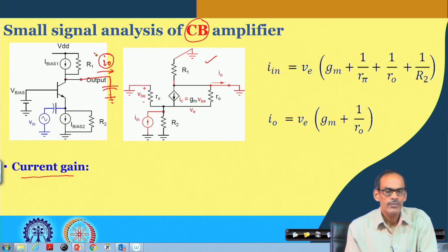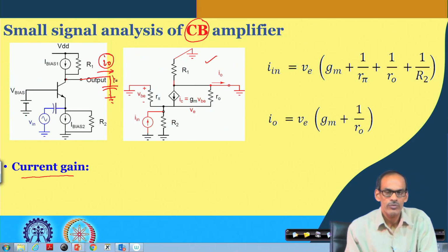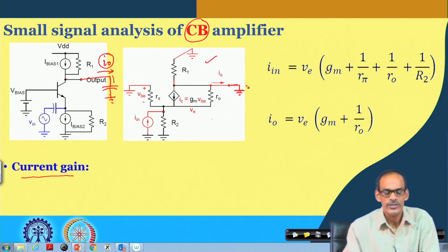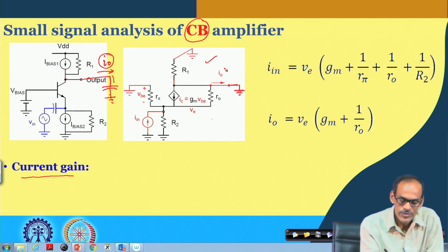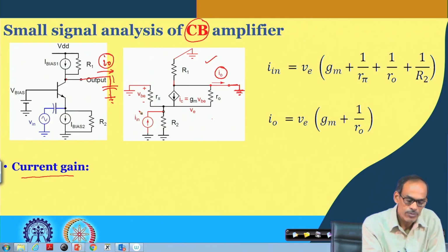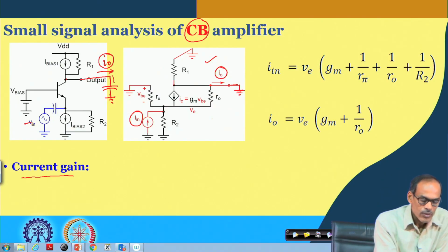And we know that if the signal is in current form, the unloaded condition should be that the corresponding terminating impedance should be 0. So, in the small signal model, if you see the corresponding situation here, this node, the collector node, is ground, and we are observing the corresponding signal current I naught. The input signal is I in. In fact, in this case we are stimulating the circuit by signal current.